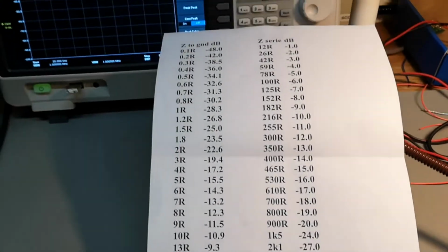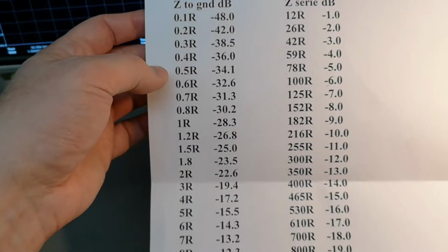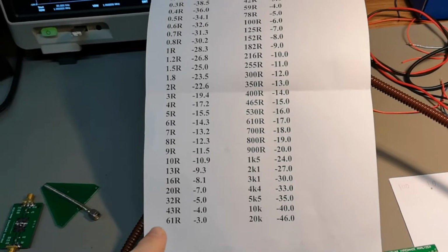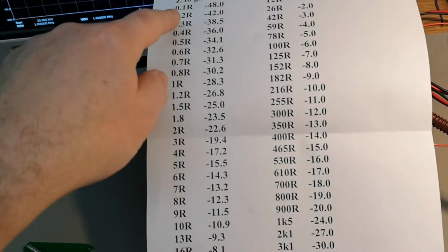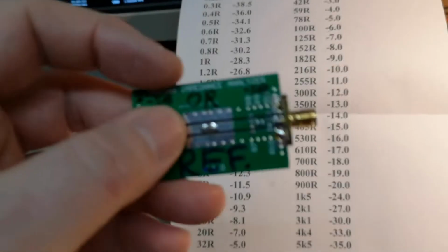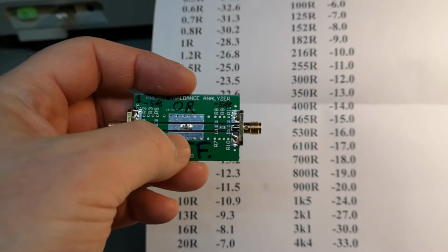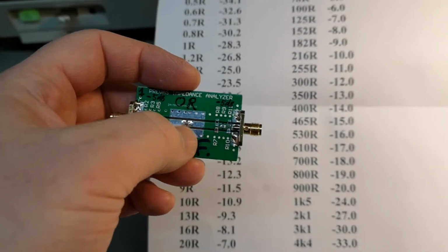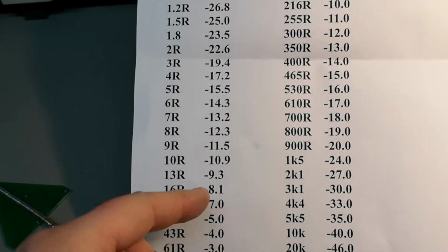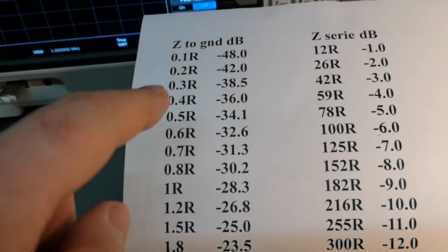To get this dB reading into impedance, I performed this calculation, or this is like a translate sheet, where I can translate the attenuation factor measured in dB that we measure on this setup. Of course, the lower the resistance or impedance you have to ground, the less signal you're gonna get, right? So the dB attenuation can be translated into an impedance in ohms.